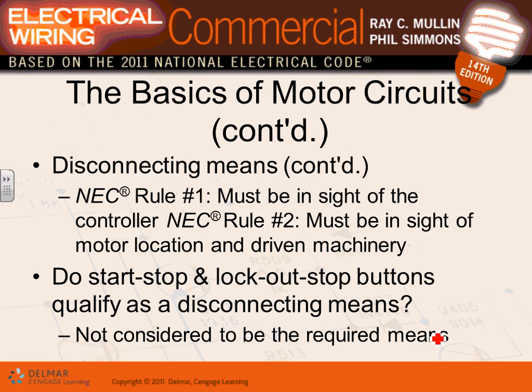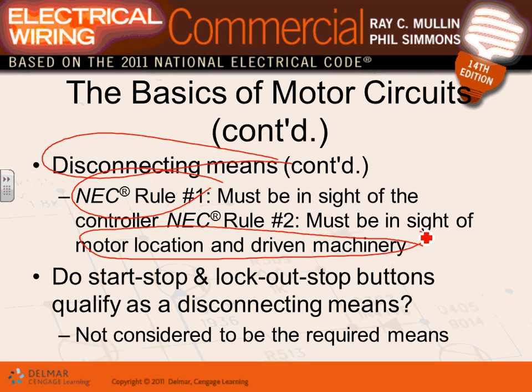Okay, for disconnects, guys, for machines and motors there are two rules. Rule number one, I'll show you in a second. It has to be within sight of the equipment as well as within sight of the controller. So your disconnects have to be within sight of your controller as well as within sight of the equipment. I'll show you a couple of pictures in a second here.